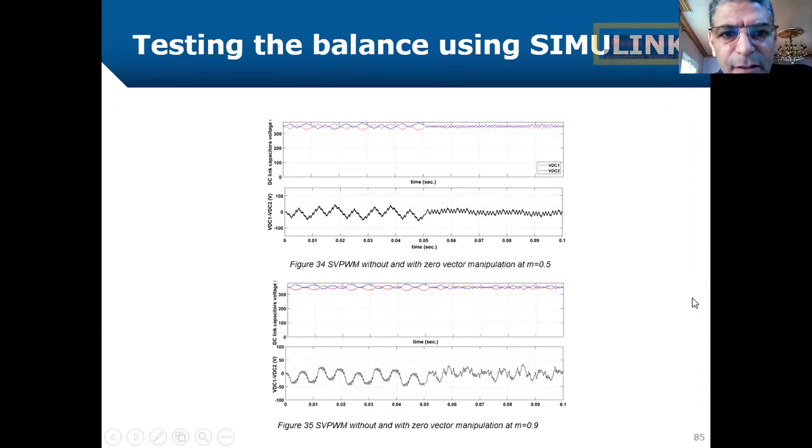And now it is time to test. Look, here with the old balancing mechanism only in the left half. In the right half, the two mechanisms are applied together, and the result is apparently better. Here is the VDC link difference. It's apparent that it has been improved. And here is VDC1 and VDC2. The same story applies here. There is improvement in the VDC for modulation index 0.9.